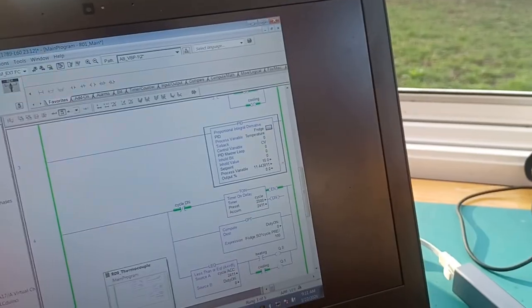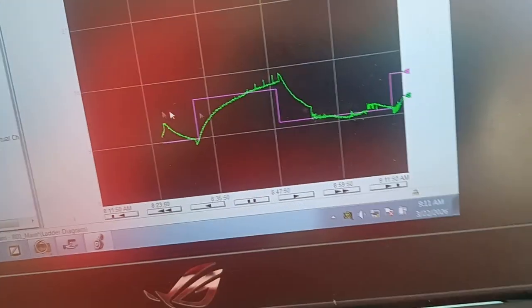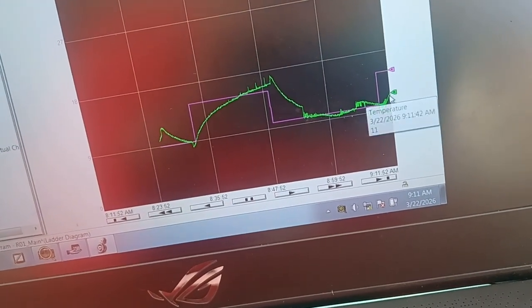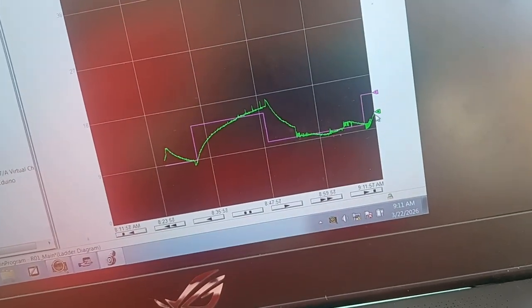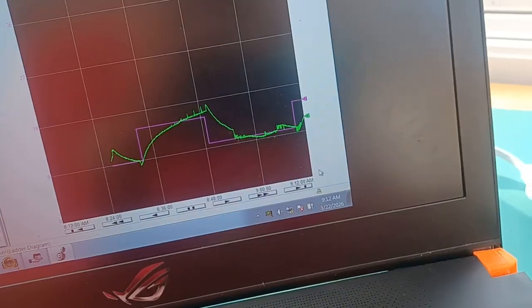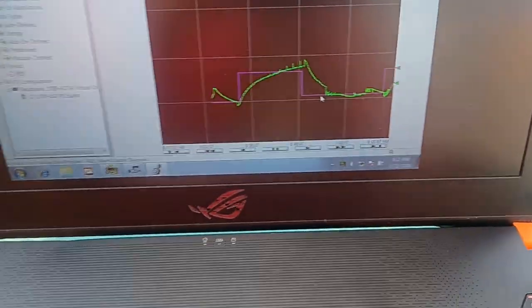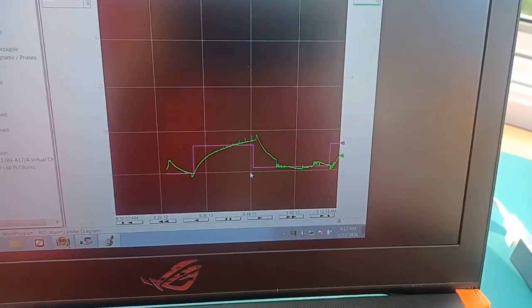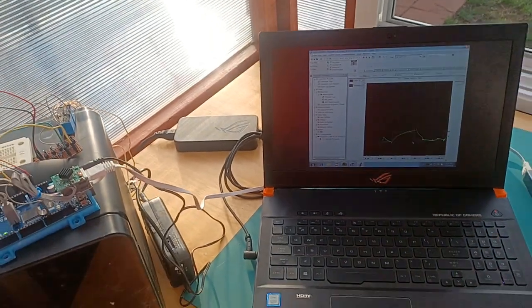But for now, go back to the trace. That's where the process is heading to 15. So it's allowing the thing to heat up. It's running less and less. I could add the output on and off here, so you can see how it changes the duty cycle. So the Peltier stays less time on, just like you expect with a proportional time on function. But that's pretty much this week's project.